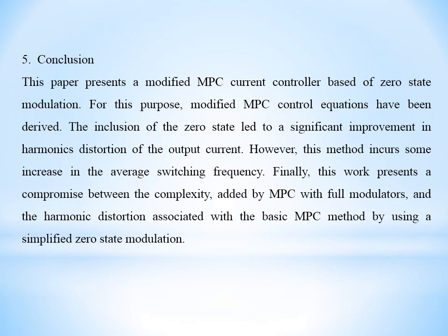However, this method incurs some increase in the average switching frequency. Finally, this work presents a compromise between the complexity added by MPC with a full modulator and the harmonic distortion associated with the basic MPC method by using a simplified zero-state modulation.